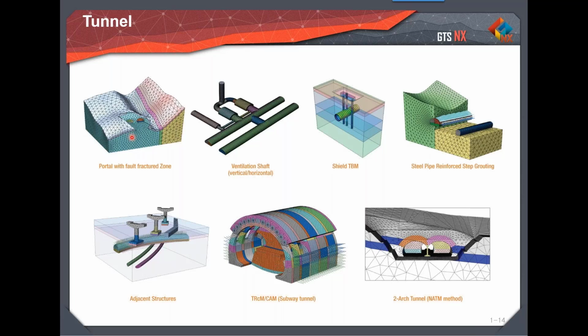And then portal stability, as well as infrastructure, or you can consider this kind of model very similar to your energy storage scenarios. You can do that kind of modeling in this software. In tunneling engineering, the entire behavior of the tunnel depends widely on the type of excavation method we use, whether it's the shield TBM method or the NATM method. You can apply those methods very easily in the software, because it's just a construction sequence that we are defining, and whatever sequence we are really interested in can be easily simulated here. And then of course you can integrate with your structural tool.